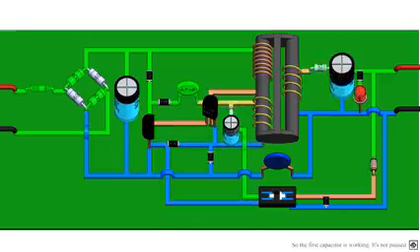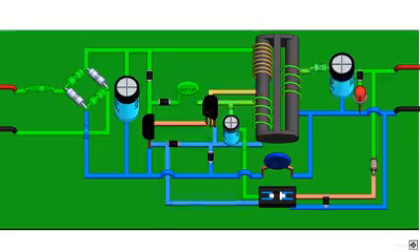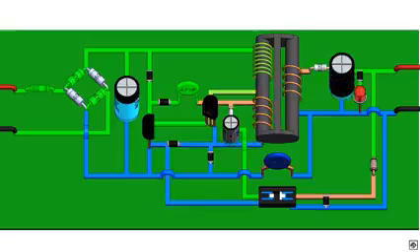Now you would have the question, why not directly convert AC to DC instead of this? This is because for the normal power supply, which is at 50 Hz, the size of the transformer and the capacitors are large. They cannot be mounted in a small charger like this. Hence, in the charger the 50 Hz frequency is converted to 50 kHz. This reduces the size of the transformer and capacitor required in the circuit. So to change the frequency of AC, first we have to convert it to DC and then again back to AC.